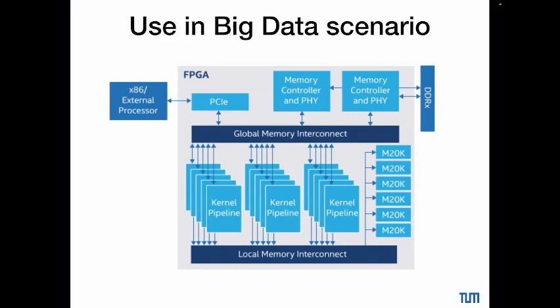So what you can do is put an FPGA in between. Here is the main memory, here is the processor, and things like searching for relevant records can be done on the FPGA. The FPGA has a much wider access to the DRAM and can pre-process this. You can burn this algorithm into the hardware of the FPGA, and by that you can already select the important records and only provide those to the processor.